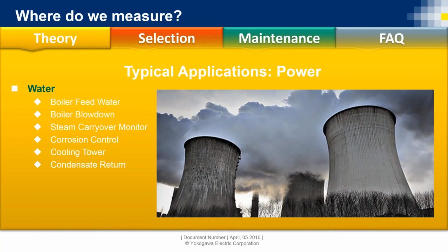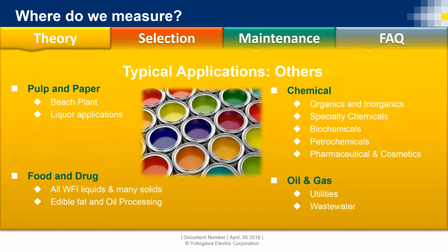Again, in power plants, you're going to have your boiler feed water, you're going to have your boiler blowdown. As your scaling increases, that conductivity value will increase to a threshold where it'll indicate, okay, now it's time to blow out all of the junk left over in our boiler drum. Cooling towers, condensate return, you're going to have conductivity readings. But those are just for water quality within a plant or a process, right? However, there are applications beyond just water quality.